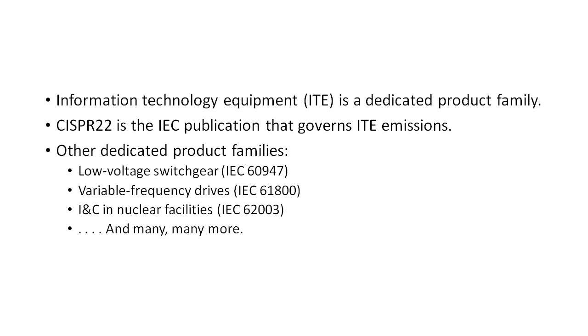So no electronic device can escape EMC testing because the generic standards act like catch-alls. An example of such a generic standard is IEC 61000-6-3, which covers radiated and conducted emissions for residential, commercial, and light industrial environments. The generic standards usually point back to specific standards for test procedures, but provide their own set of limits. IEC 61000-6-3, for example, refers back to CISPR 16 for the procedure for measuring conducted and radiated emissions, and CISPR 22 for the procedure for measuring conducted emissions from Ethernet ports.